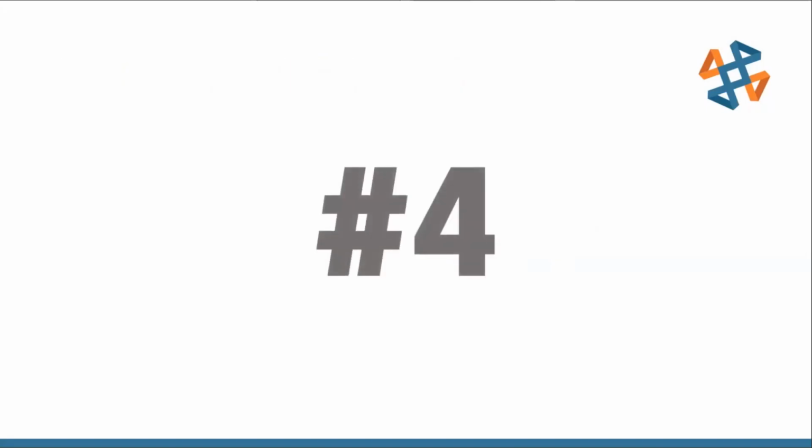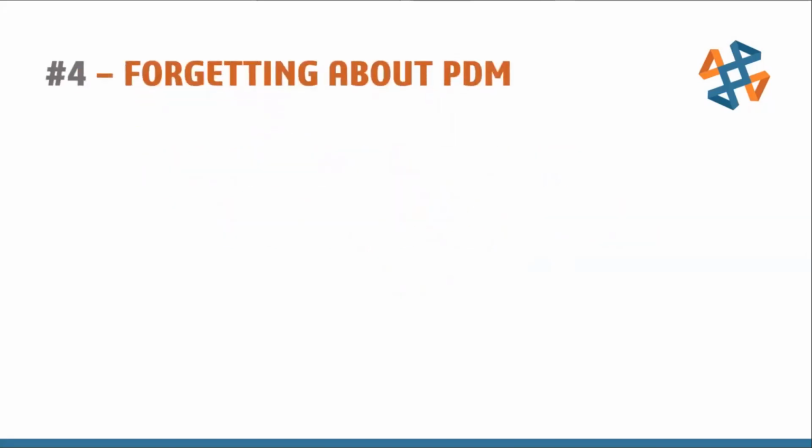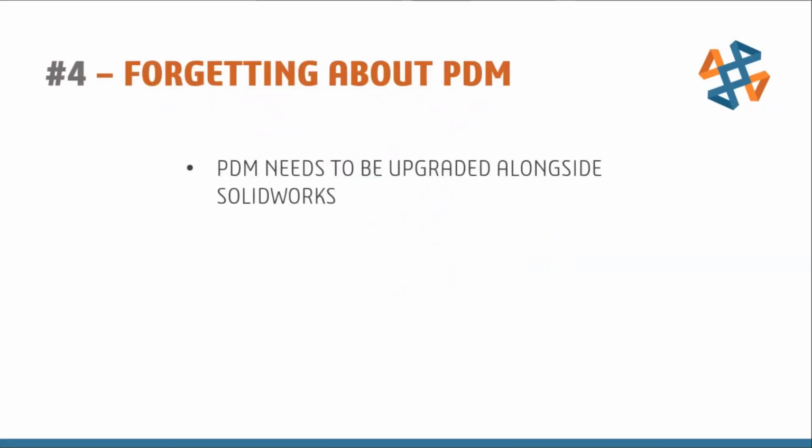Number 4, forgetting about PDM. And this goes along with other add-in products as well, but PDM is the one that we see the most. And the reason that this is a number in our top 10 things is because PDM is extremely important as you upgrade SolidWorks. If you also have PDM, PDM needs to be upgraded alongside SolidWorks.